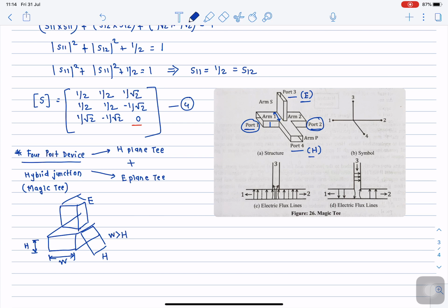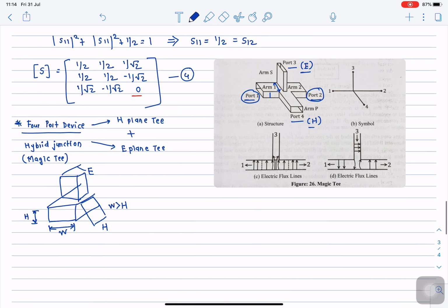Okay, so you can divide the power equally, with the same polarity as well as with opposite polarity. Both things you can perform using this magic T power divider circuit. As the source is connected to one of the side arms with a matched termination at the other side arm port, the load impedances are connected to the ports of the collinear arms. The magic T exhibits certain properties when the terminations are interchanged between the side arm ports and the collinear ports.